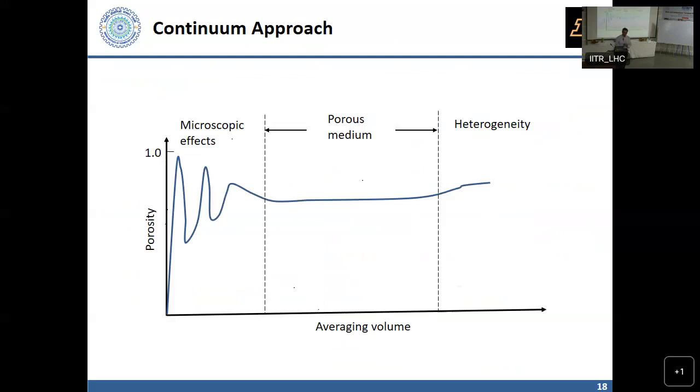That is important. It becomes important in continuum approaches at other places too, because when we derive the governing flow equations, the mass conservation equation, Darcy's law, constitutive relationships, we try to do a mass balance. To get differential equations which help us understand flow, we set in the limit the size of our elements, delta x, delta y, delta z, all going to zero, for the difference equations to become differential equations and become a continuum.